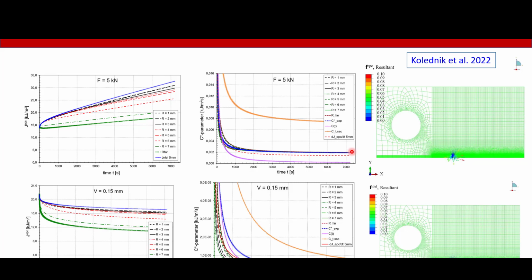And people have shown correlation of dA/dt with C*, which does not make much sense, because what is C*? That is a question which cannot be answered. So crack growth velocity is related to a parameter which is not describing crack driving force or material's resistance. Okay. But in some cases, C* can define the stress field at the crack tip.